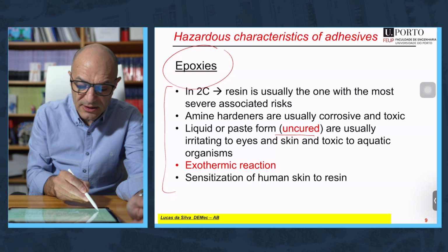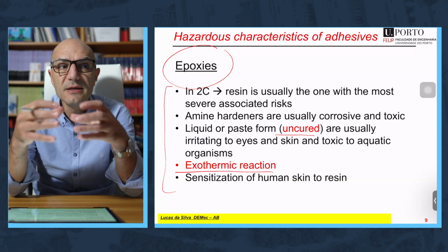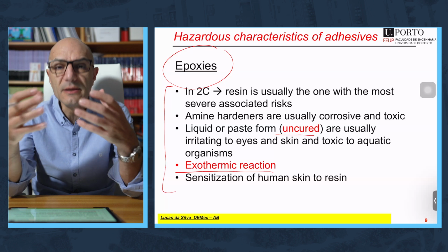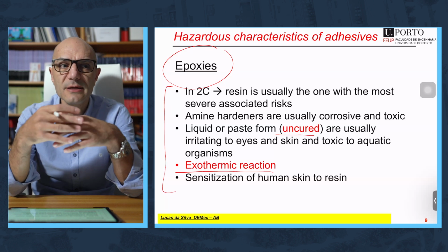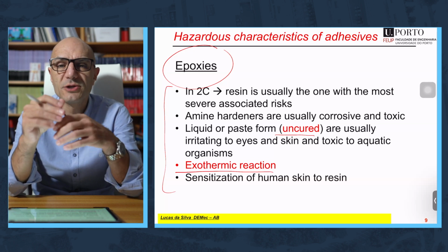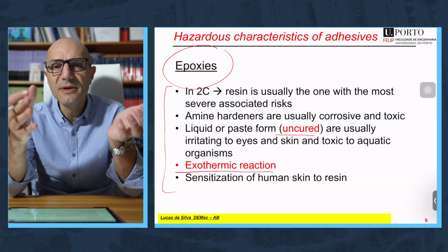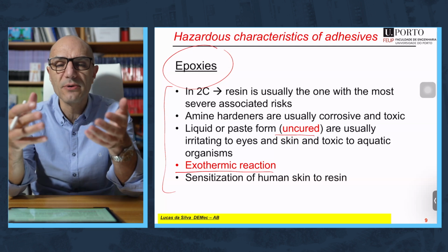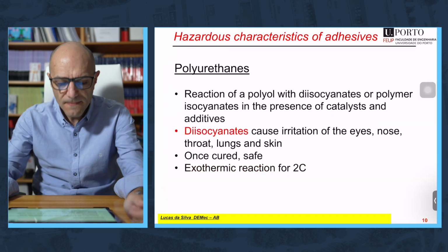During the cure, this adhesive has an exothermic reaction, so that means the adhesive will heat, so we should be careful. We shouldn't use too thick bond lines, but the adhesive maker will tell you what is the limitation in terms of bond lines. Typically not more than 1 or 2 millimeters. If you use thicker bond lines, then it might even burn the adhesive.